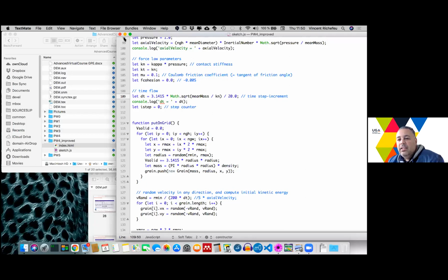But it is not the way it is used. Actually, kappa is here only to define an order of magnitude to set your stiffness. And you are in charge of defining what is the pressure to be considered to define the kappa to be used to define the stiffness, the pressure stiffness, the friction stiffness. A question by, yeah, please.